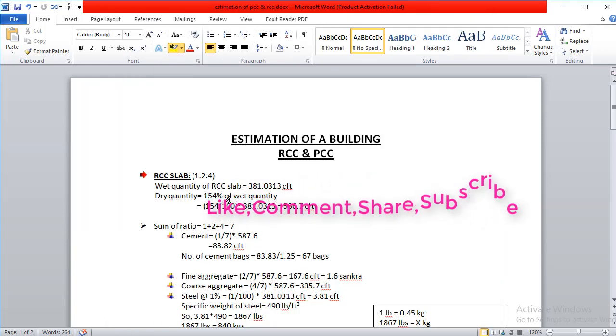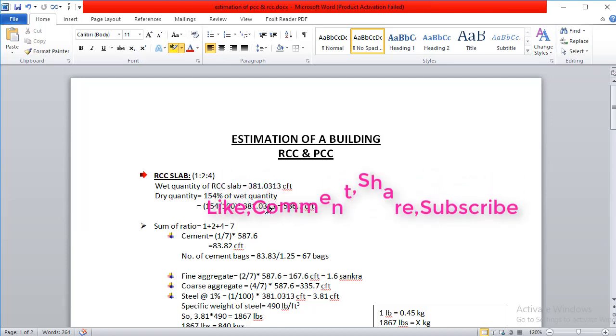Now the dry quantity is 154% of the wet quantity. We already know that. So 154 divided by 100 multiplied by 381.0313 is equal to 586.7 cubic feet. Next I find the sum of the ratio, which is 1 plus 2 plus 4, equal to 7. To find the quantity of cement, the ratio for cement is 1. So 1 divided by the sum of ratio, multiplied by the dry quantity of this RCC slab. So I will get the quantity of cement, 83.82 cubic feet.